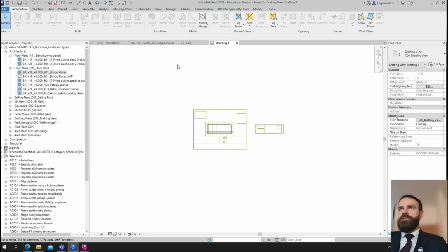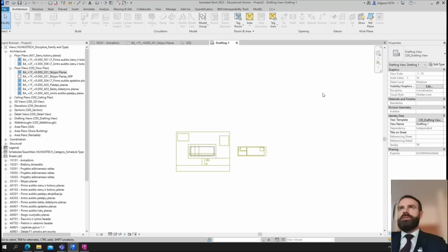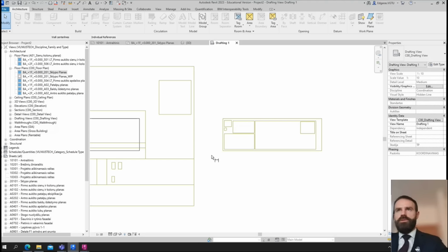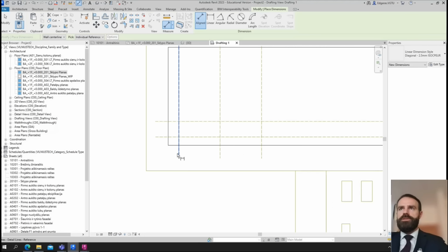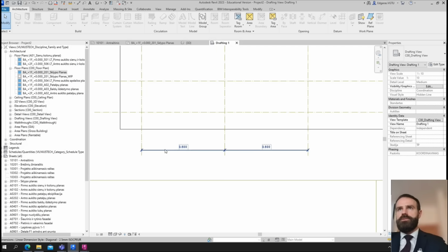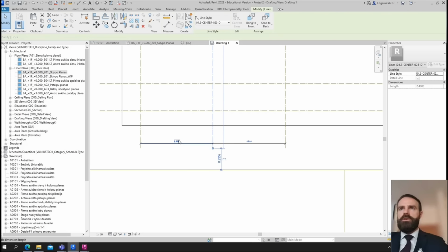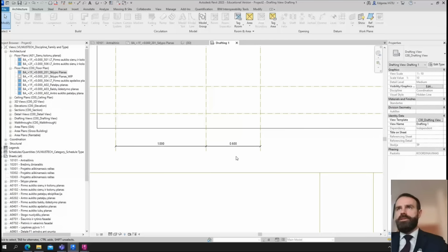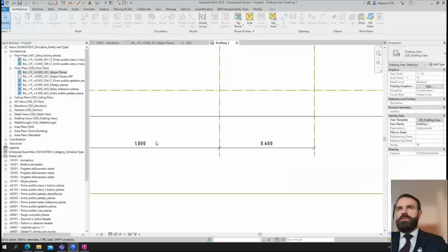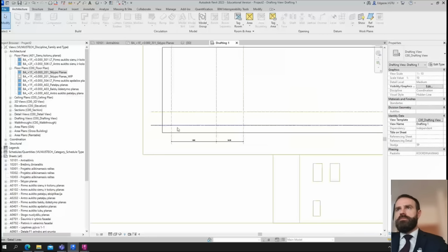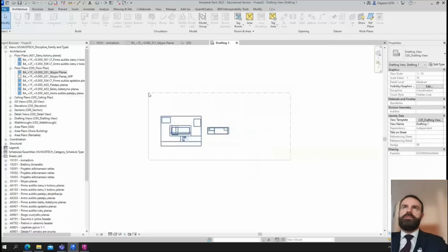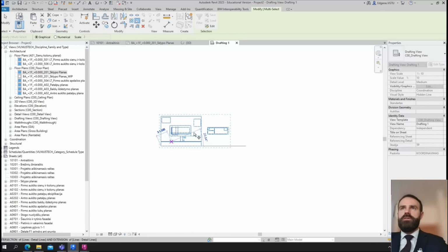And this one is like AutoCAD modeling space, and you can put dimensions, temporary dimensions, like these ones. So 0.8 meters, and I can say it's 1 meter or 25 meters and so on. So let's say now this is a very small drawing, so I just select, choose scale, and scale it by 50 times.